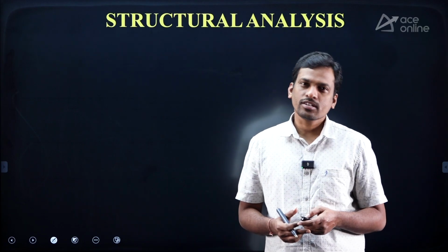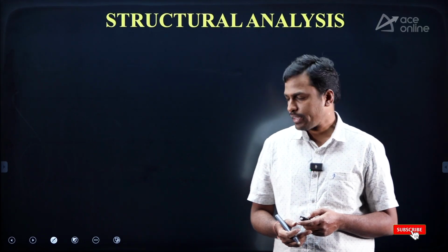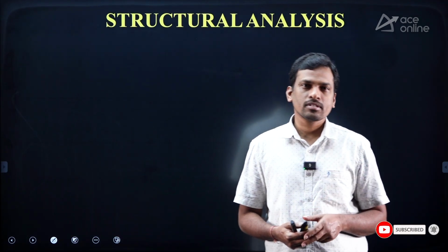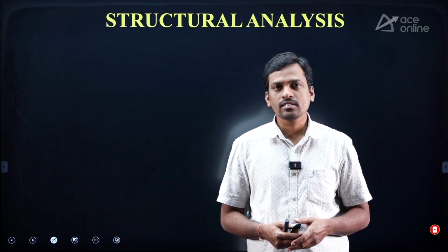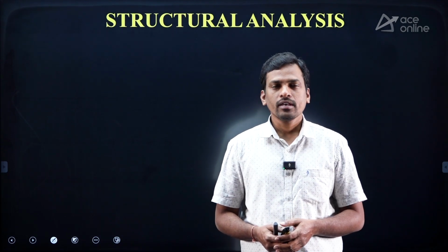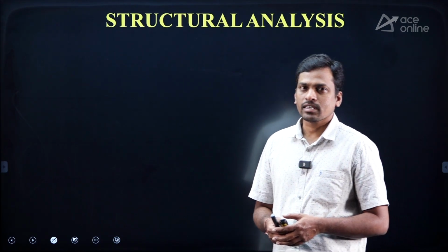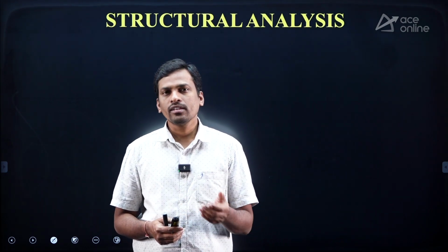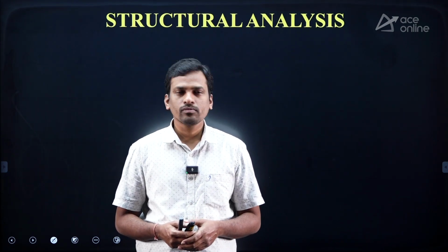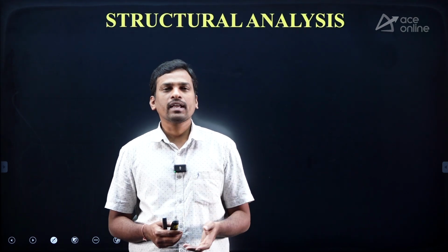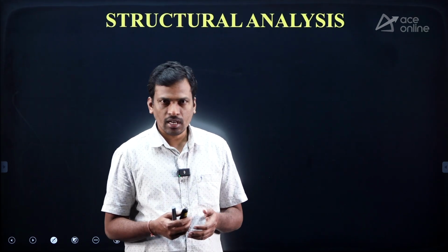The subject is structural analysis. In the introduction chapter we require two concepts: one is support reactions, and another one is the number of equilibrium equations. Given support reactions: fixed support has 3 reactions, hinged support has 2 reactions, roller support has 1, and vertical guided roller has 2 reactions.